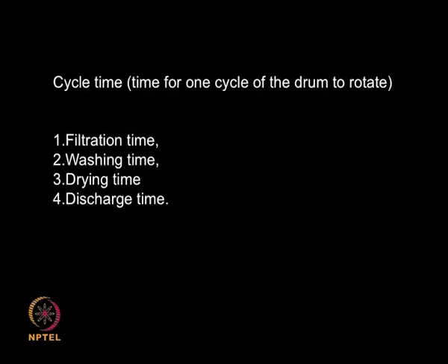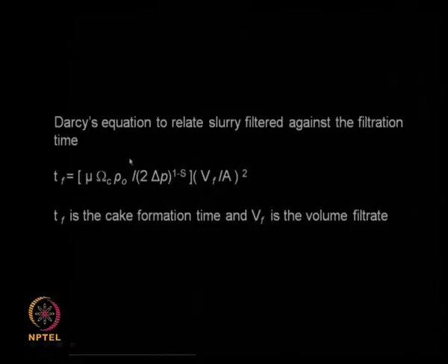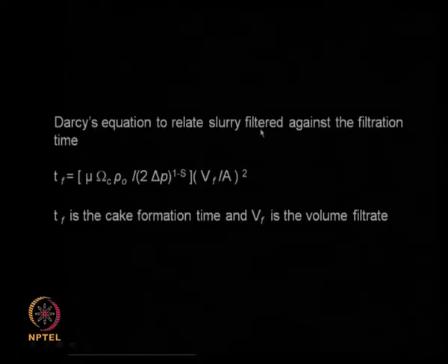Okay. So the cycle time, that is the time taken for the drum to start from the slurry tank, go round and finally reach the slurry tank, is made up of 4 steps. One is called the filtration time, second is the washing time, then the drying time, and finally the discharge time. All these add up to give the cycle time. So we can still use Darcy's law for calculating the filtration time.